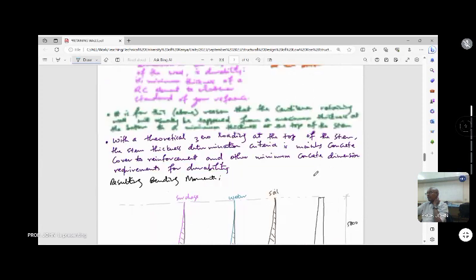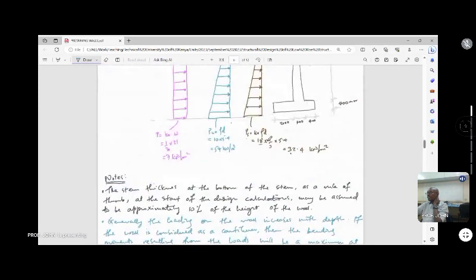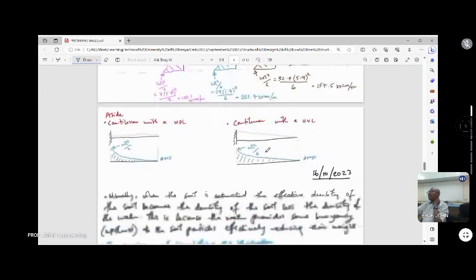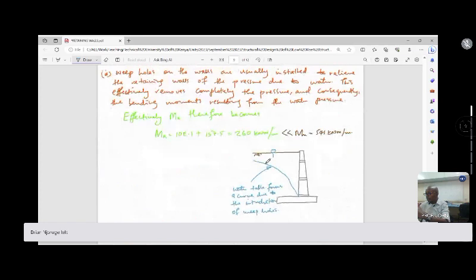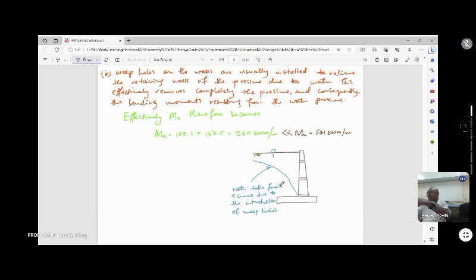We worked with the true density of the soil, which is 18. If we had worked with the 8, which is 18 less 10, then we would have had to come back and put back this loading. So these assumptions that I made were because of what I thought we would discuss a bit later.